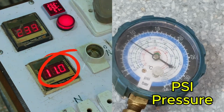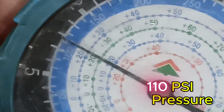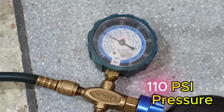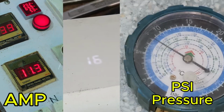If we check the refrigerant pressure, it is proper. At this moment, the unit's pressure is 110 psi. This pressure is perfectly fine for the refrigerant, meaning the refrigerant condition in this unit is entirely okay. I will keep monitoring the amperes until the unit starts displaying an error.